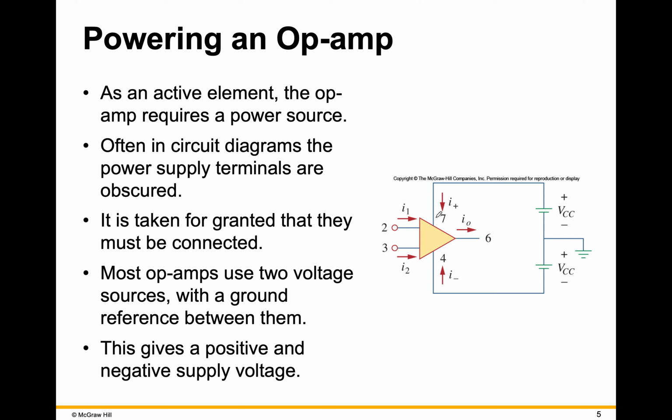So here's just an example to show how power is hooked up to an op-amp. Typically, people will refer to these voltages as the rail voltage. There's usually in a given op-amp a specification on what the rail voltage can be. It typically varies anywhere from 1 to maybe as high as 10 volts, depending on the op-amp. You rarely see op-amps that will take voltages over 10 volts.